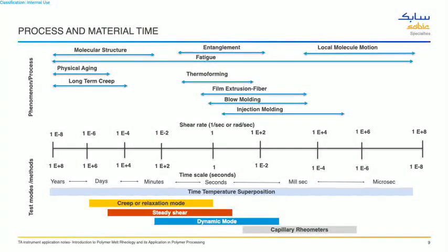To understand the whole time spectra, how the material behaves in the solid state, for example long-term behavior, long-term creep, physical aging, molecular architecture, you have to test the materials at those particular time scales or relevant shear rates. And more importantly, this entanglement concept I'm talking about is very important for all the processes, the properties which we're going to attain.